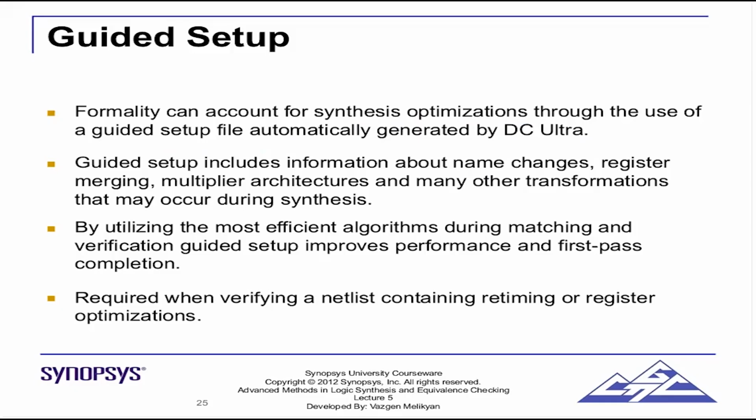Why? Because register merging will reduce the registers. So for example, if two or more registers are merged together, the number of registers in the implementation now will be fewer than the ones present in RTL. So register merging is very important.